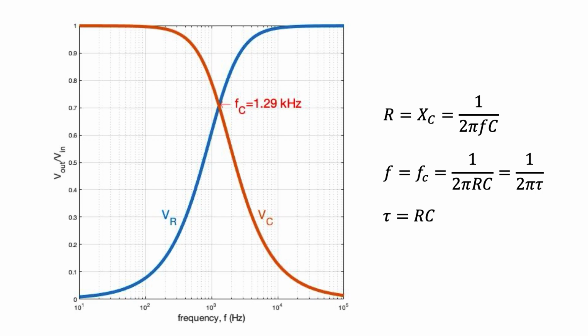It only allows the passage of signals at high frequencies. In contrast, if you use the capacitor as the output voltage, any input voltage will be filtered out at high frequencies, starting from the cutoff frequency. It only allows the passage of signals at low frequencies. Both configurations act as a filter. Taking the output across the resistor is a circuit configuration called the high-pass filter, and taking the output across the capacitor is a circuit configuration called the low-pass filter.